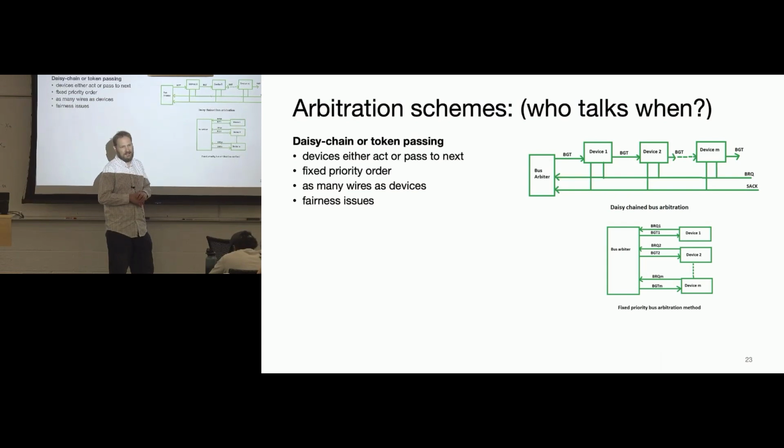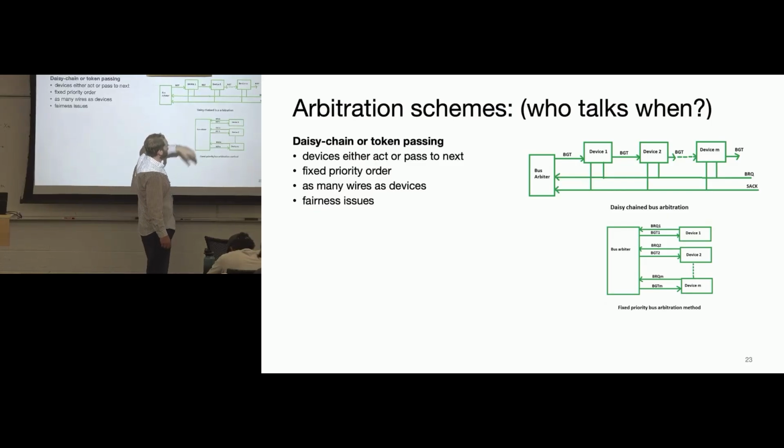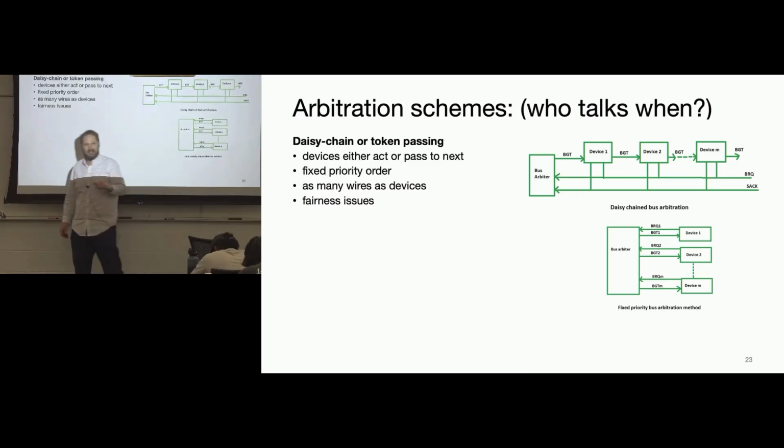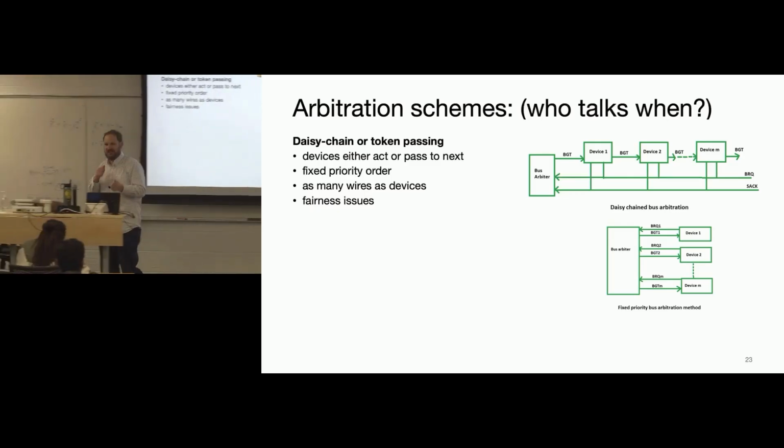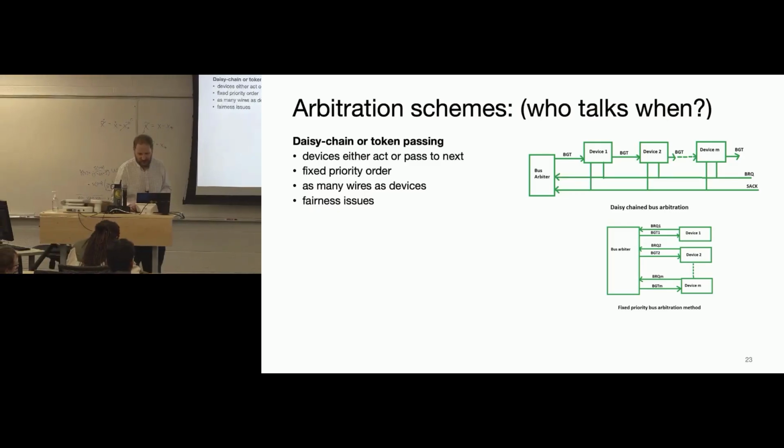Assert the select line for the peripheral we want to talk to and deassert all the other ones. Yeah, so you said you were going to use the select line to select the actual peripheral, so that was the way to arbitrate, and then the address bits talk to individual registers inside that peripheral. And then there's a bunch of different ways because it does get complicated. There are some bus protocols where there are no select lines whatsoever, and now you have to find some other method to decide who's talking and when they should talk.